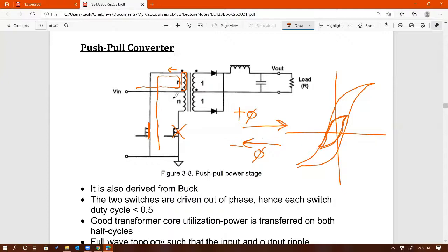I just have another question. What mode is that operating in? Well, we have an output inductor right there. If you look at the output inductor, current is always positive, always to the right, so that's still CCM. Okay, got it, thank you.